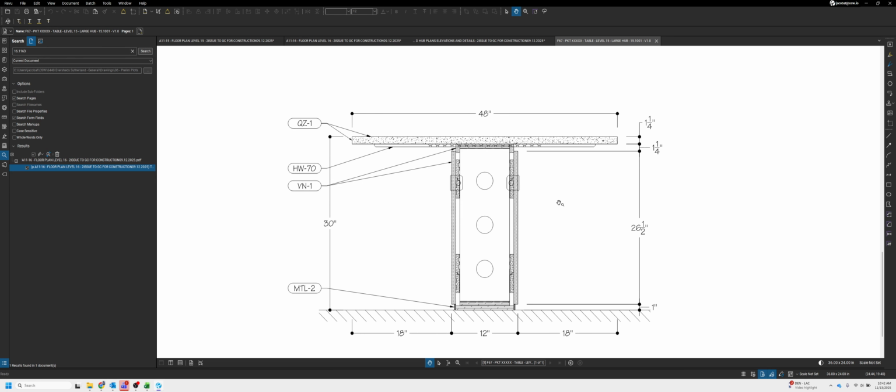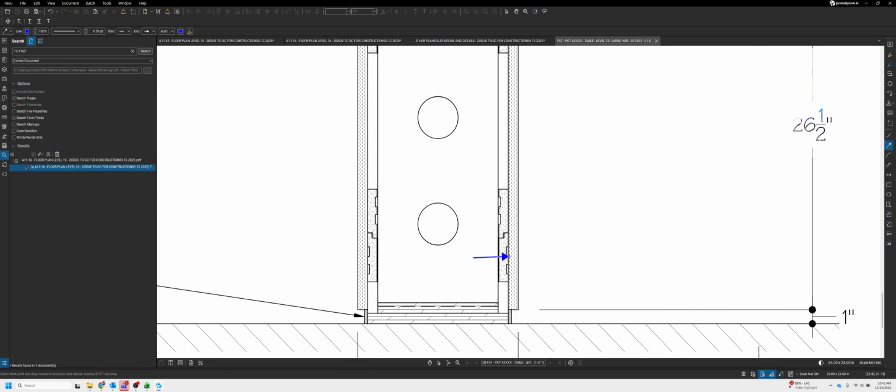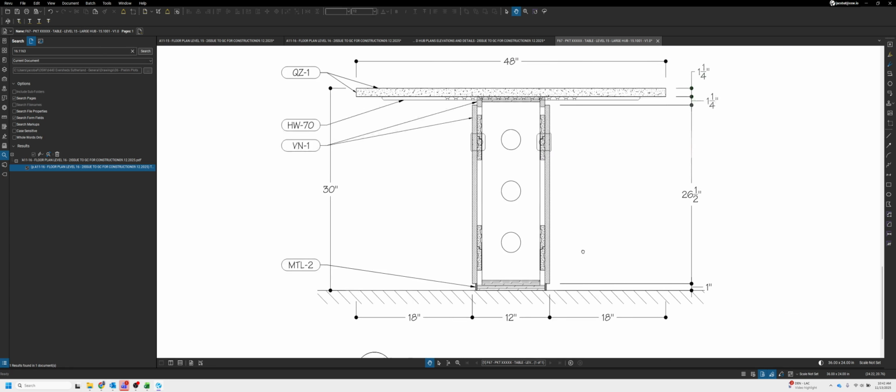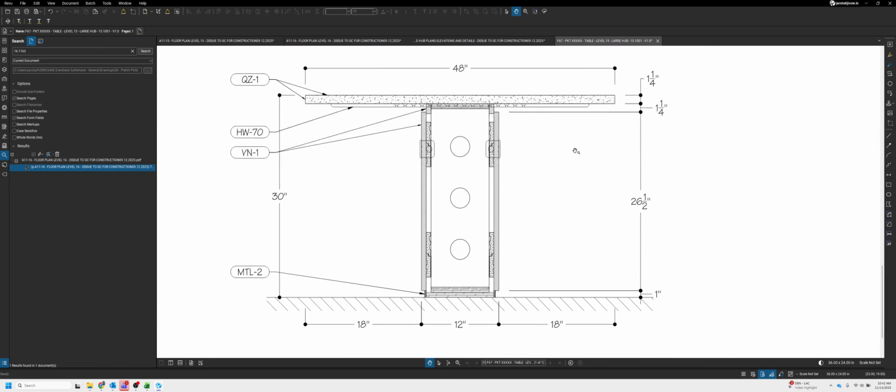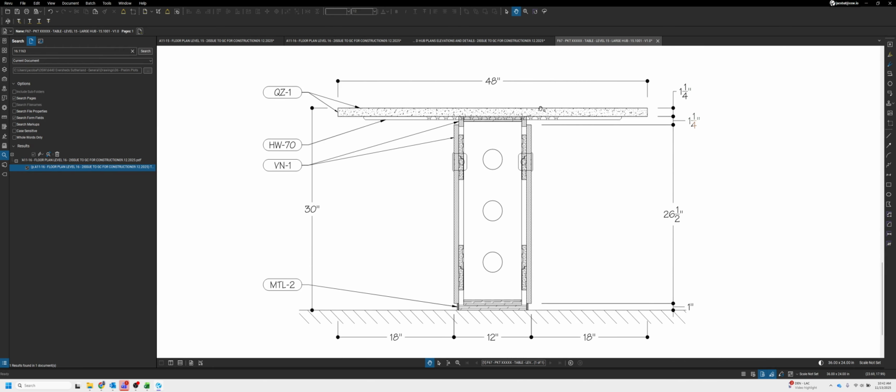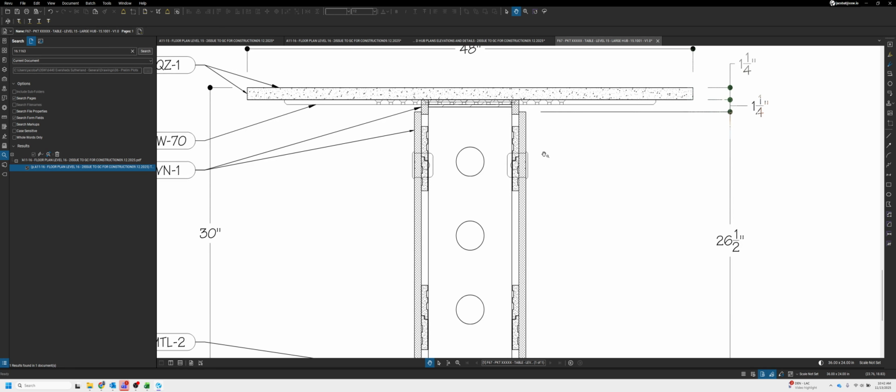Because if you can get in here, it makes it easier to actually frame and build this thing without putting face fasteners like screws through the front like this, because you don't want to do that. So what I have drawn here is panel cleats on both sides of the island frame, and we're going to use that on our island as well. You could also potentially use integrated cleats here if you'd like to, that are routed into the die wall framing. We did talk about those during the die wall framing video too, but you can do that too.